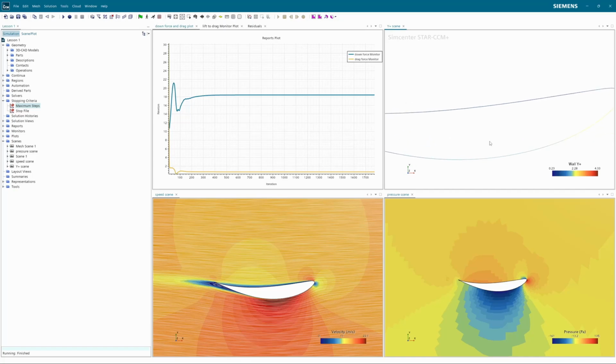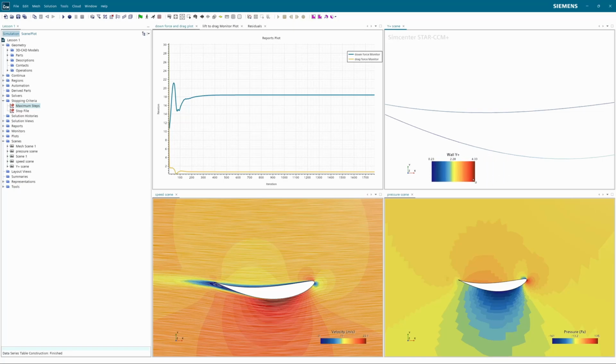All right. So, a couple things that we can check and control. So firstly, there is the wall Y plus. Now, as you can see, it doesn't get the numbers bigger, but it clearly shows that along this entire thing, the wall Y plus value is never exceeding 5, which is correct, and that way we can ensure that the boundary layer has been properly simulated.